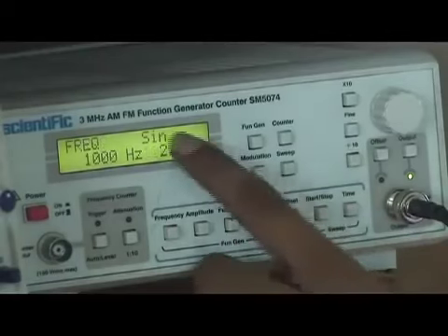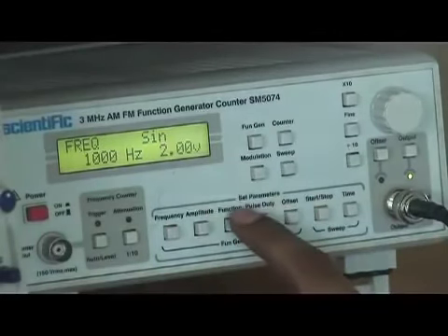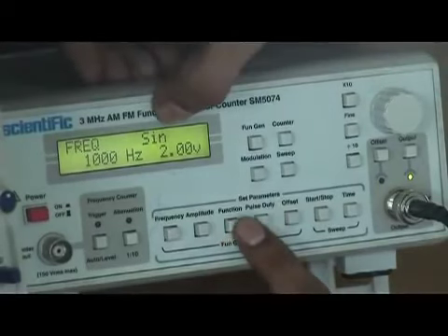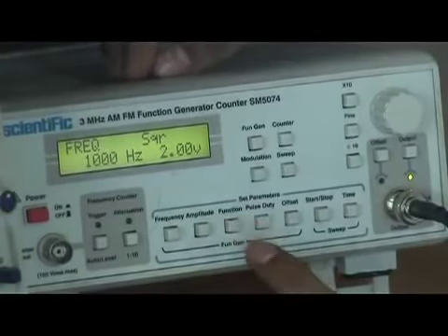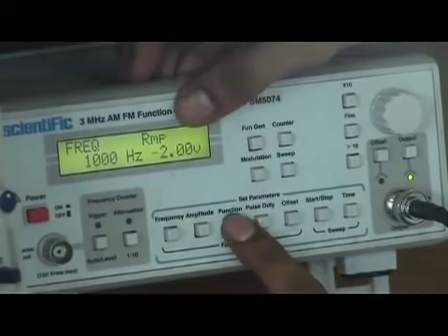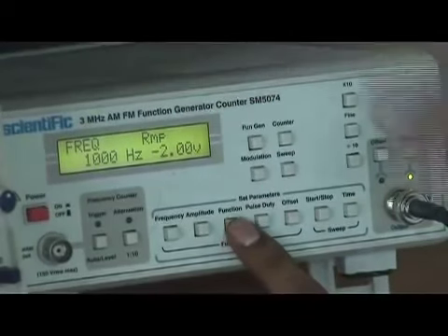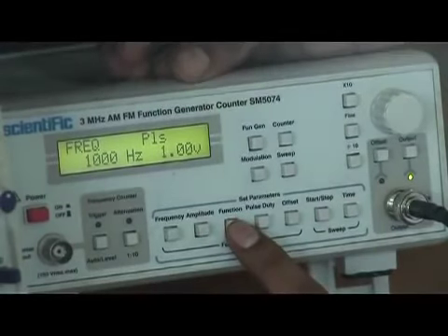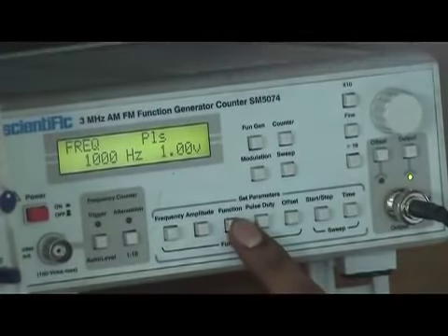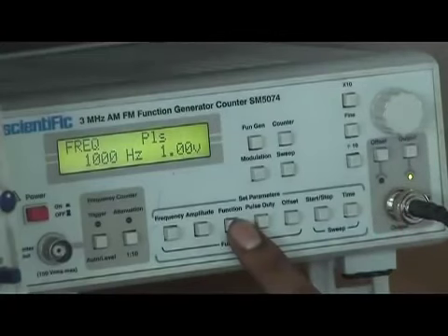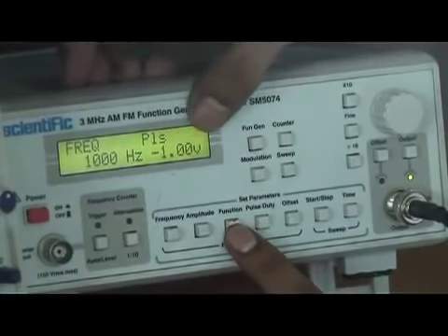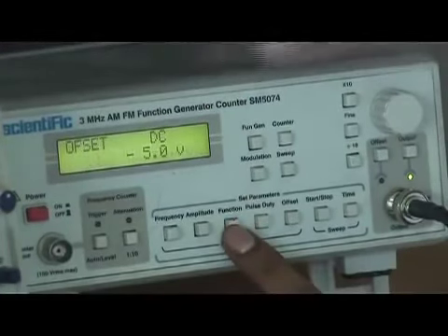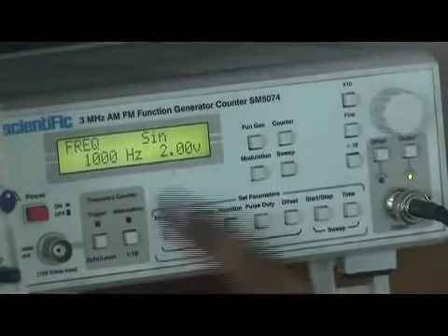Now what is the function? My function is sinusoidal. You can change the function from sinusoidal to various functions, like triangular. If you press it again, square. If you press it again, this is again a square. Ramp, it's 2 volt. Again, ramp minus 2 volt, means a negative ramp. This is pulse 1 volt, because when we say pulse, it denotes only from reference to upper level or reference to below level. When I press it again, it says a pulse for minus 1 volt, means below. Then a DC voltage, then again back to the sinusoid.